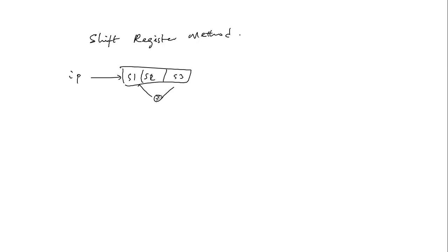Now, each code output, so that this is one possible output, is produced by sampling the output of all the modulo 2 adders once per shift register clock period, okay? So the convolution code derives its name from the fact that the output is obtained by the convolution of the input sequence with the impulse response of the coder.